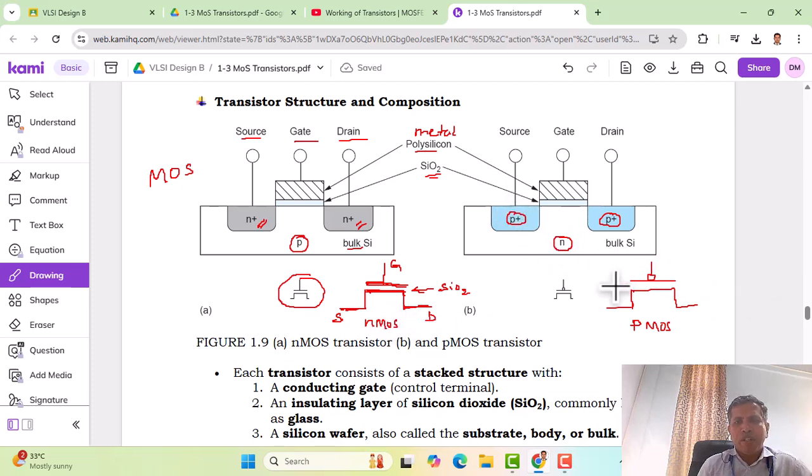As usual, here again this P region serves as a source and drain. This region is the source region, and this line shows the drain region. And once again the gap here indicates it is silicon dioxide, which is an insulator, and there is a metal here, this thick line, it is a metal layer, and the bubble shows that it is a PMOS transistor. So often we use these symbols to develop circuits of various NMOS and PMOS based circuits. We use these kinds of symbols because drawing the cross section or drawing the dimensions like this becomes very hard when showing circuits.